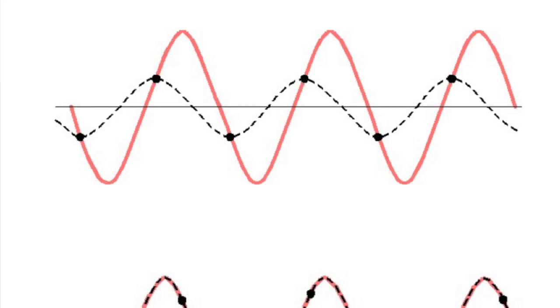And there again, if we reconstruct, we don't quite have enough information to reconstruct properly. Instead, we get this lower amplitude signal that doesn't truly reconstruct what we started with. So again, you see the amplitude distortion is the big one, and it's also phase shifted from the original signal. So we need a little bit more information, as it turns out. We need to sample slightly higher than the minimal Nyquist frequency, the highest frequency component in the signal we want to sample. We have to sample a little bit higher than that.